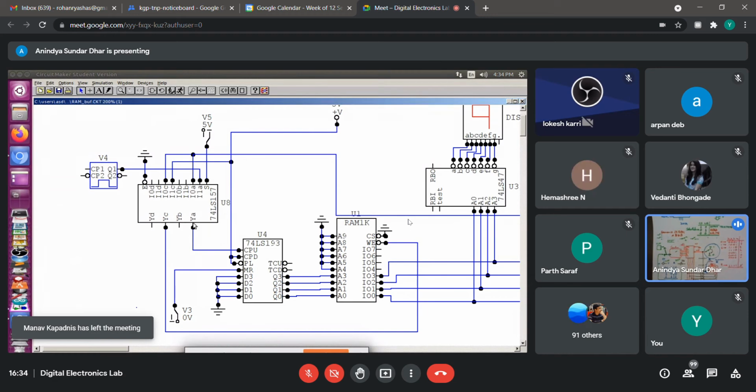So multiplexer number A is having two inputs, I0 and I1, I0A, I1A. I0 will be selected if this S is 0, other line will be selected if S is 1. Same for others also. YB output will either take I0B or I1B depending on the value of S, and so on. So I am using YA and YC, these two multiplexers. C is going to this write enable.